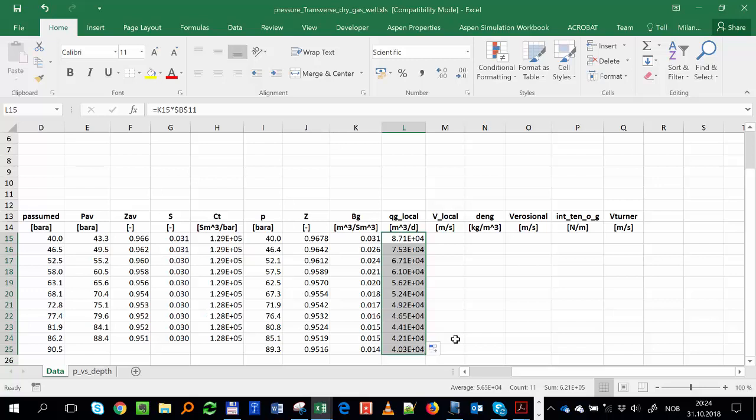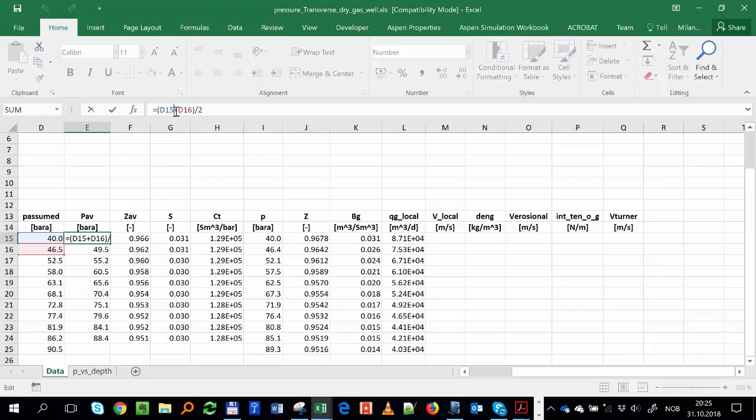But basically, it's the same tubing equation, right? But we are applying it now on a segment because we are not interested in the inlet or outlet of the tubing. We are interested in what happens along the tubing. And that's very useful for many things. Actually, in multi-phase flow, we have to do our calculation in this manner. Yes? Check the form of the average. This one here? Yes, it's the same for all.